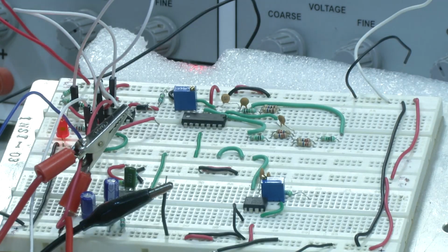Now, if we connect the output of this to a digital counter, we can easily count how many pulses we are getting. And if we create a clock cycle for a particular time period, the number of pulses we get gives us the BPM, beats per minute. So, we have seen from the individual subsystem point of view whether it is working as per our requirement or not.